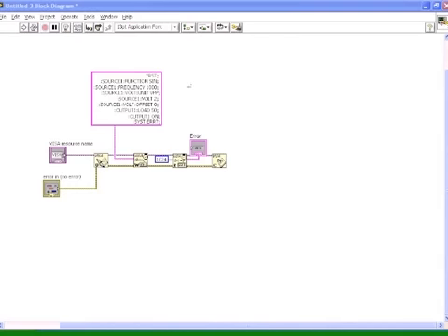Now if we take a quick look at the SCPI commands here, you can see that I'm setting the function generator up on channel 1 to have a function of sine. I'm setting the frequency to 1 kilohertz. I'm setting the units to volts peak to peak, and then I'm setting the amplitude to 2 volts peak to peak. I'm using 0 offset, and then I'm telling the output on channel 1 to expect a load of 50 ohms, and then I'm turning output 1 on. At the end of it, I'm sending a SYST:ERR? just to make sure I didn't make any mistakes in my SCPI commands.